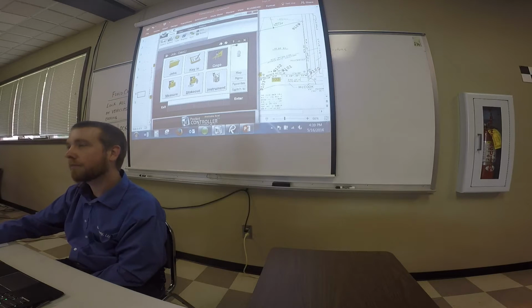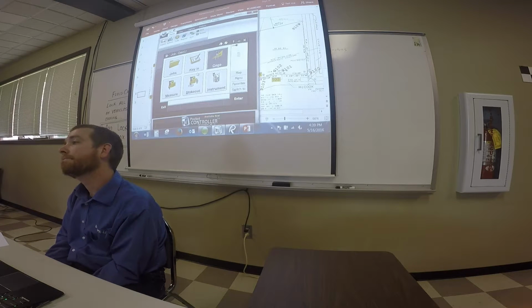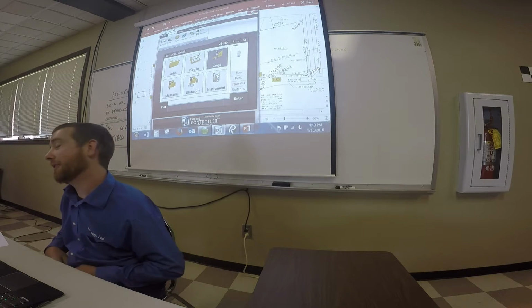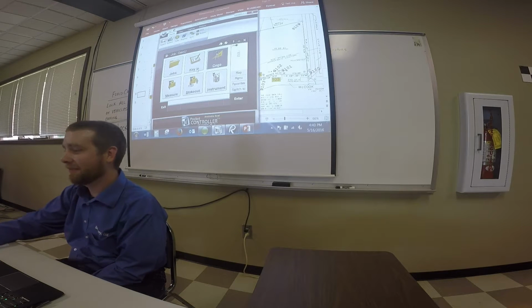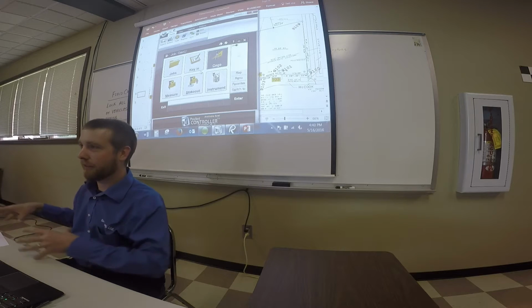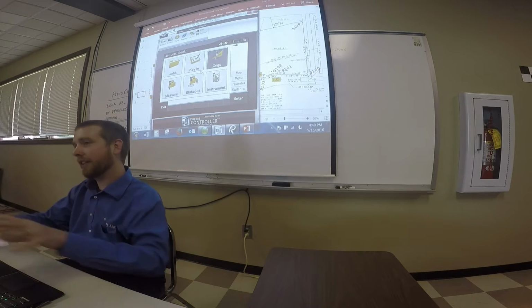Let's discuss this if you don't know. What's our preference: move our field data to the plat, or move our plat to our field data? Plat to the field data. If you move the field data, it erases all of the turned angles and distances from the raw file, and we don't want to do that. So you leave your traverse and your points alone, and move and rotate the plat as needed.